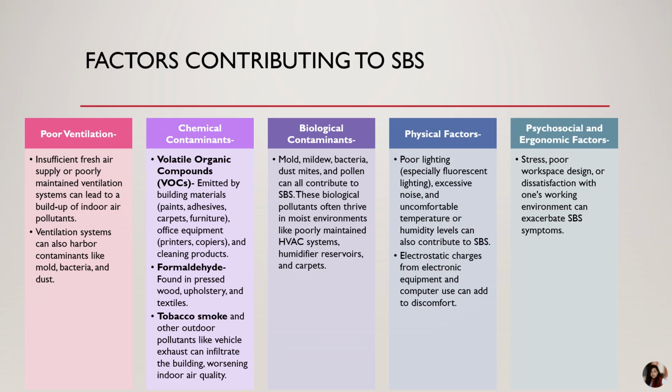Biological contaminants are nothing but bioaerosols which have the presence of mold, bacteria, dust mites, pollens. These are the contaminants which become more comfortable in those environments, and they start to multiply because of the poor maintenance of HVAC systems. And physical factors are nothing but poor lighting systems, especially when we are using fluorescent lighting, excessive noise, uncomfortable temperature or humidity level. These are all contributing to SBS. Sometimes electrostatic charges from electronic equipment also can add to the discomfort.